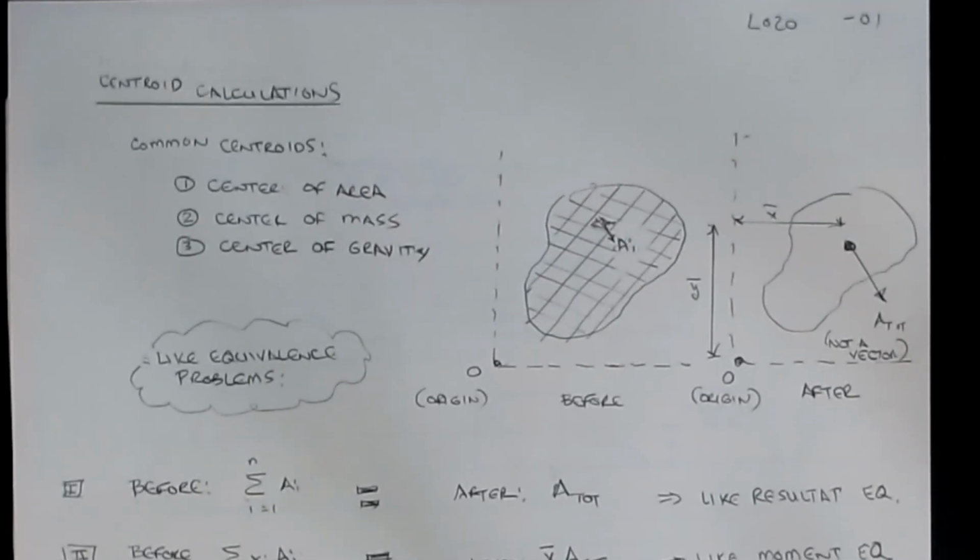In statics, centroids are a very important calculation for figuring out properties of an object. Ask any engineer who's ever done any sort of design or analysis work, and they have done a whole lot of these types of calculations, finding out where the center of a force is being applied, or where the center of mass of an object is. They're very necessary for calculating other things, such as section properties like the moment of inertia or the second moment of area. This is the starting step for those calculations.